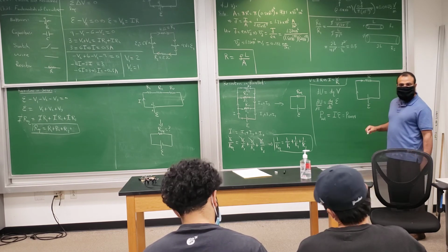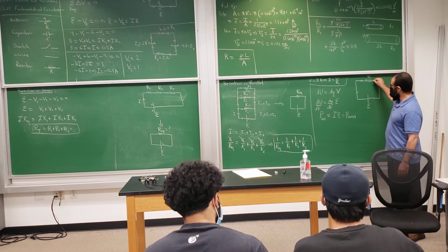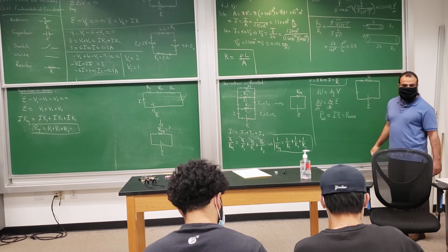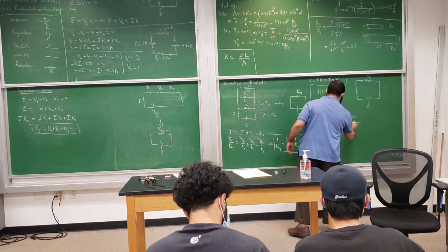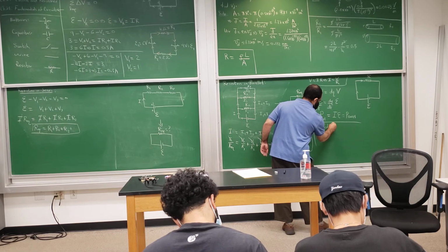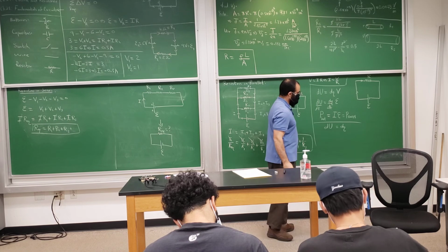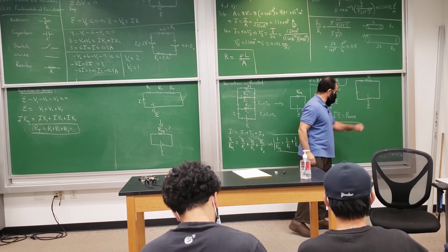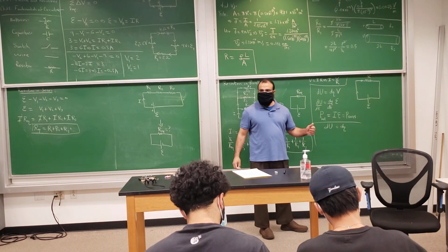So where is that power going? Well, the current will flow through here, it will go through the resistor. So let's see the dU for the resistor, what would it be? dU for the resistor would be dq, it's the same charge. So the battery took a dq from here and then it went through the resistor, times the voltage drop, right?